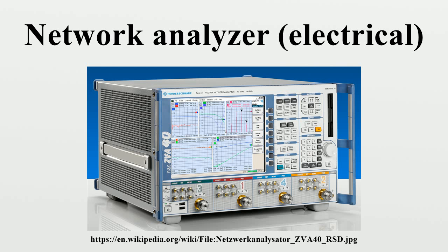A vector network analyzer achieves highly accurate measurements by correcting for the systematic errors in the instrument, and the characteristics of cables, adapters and test fixtures. The process of error correction, although commonly just called calibration, is an entirely different process, and may be performed by an engineer several times in an hour. Sometimes it is called user calibration, to indicate the difference from periodic calibration by a manufacturer.